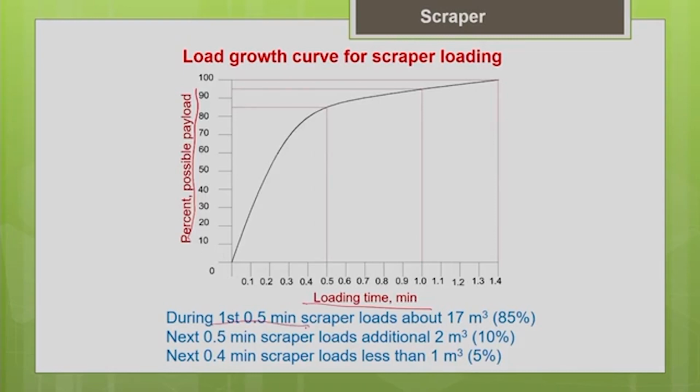during the first 0.5 minute, say the scraper capacity is 20 meter cube. The maximum capacity of this scraper which we have considered here is say 20 meter cube. Now, you are loading the material into the bowl. For the first 0.5 minute, your payload percentage is 85%. In the first 0.5 minute, I have filled 85% of the scraper bowl.